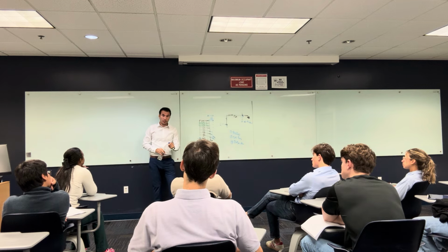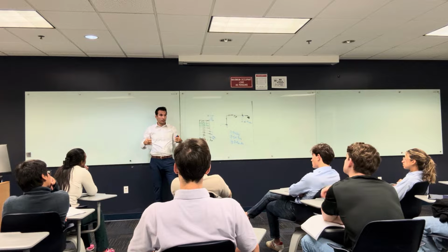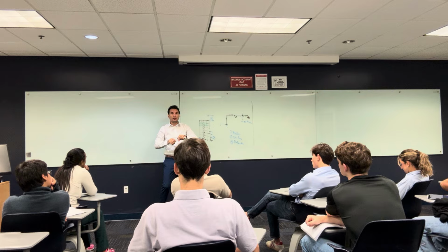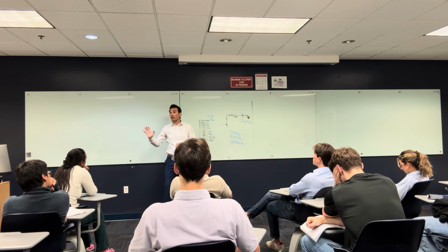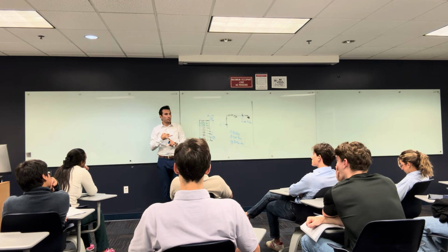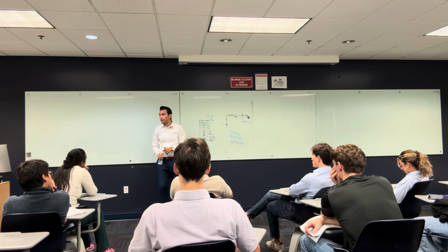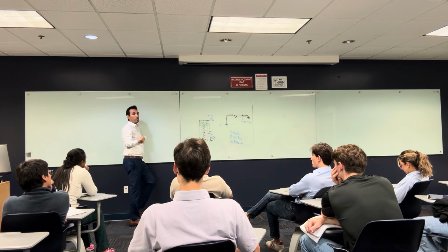When you say stiffness of an element, there are multiple stiffnesses. Are you asking about the axial stiffness, the bending stiffness, the shear stiffness, the torsional stiffness? Every structural element has different types of stiffness. It depends on its geometry, the Young's modulus, the inertia, and the cross-sectional area. All these affect the stiffness of the element. It also depends on the boundary conditions.